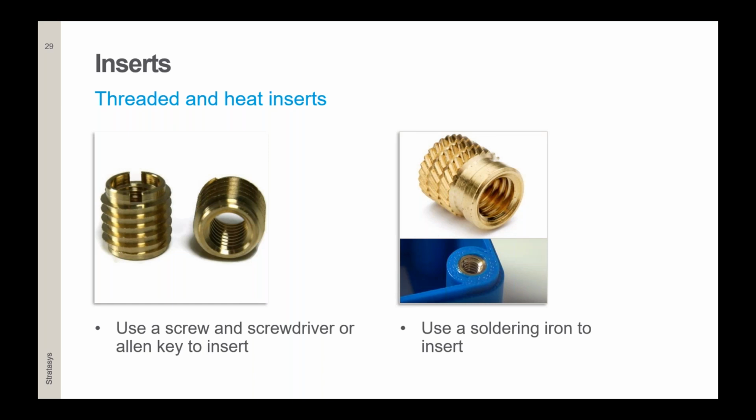You also have to pay attention not to overheat the insert, as the material can melt and deform itself. These inserts are quite a good option if you want to avoid designing slots for nuts. Just simply put a hole according to the manufacturer's data sheet, and then after the print, the insert can be put in the model. They also work quite well with all FDM materials.